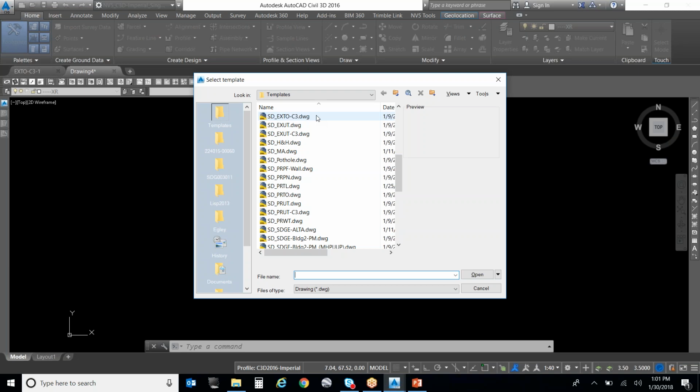So that'll be part of Mark's workflow here when he goes and builds a surface, starting with the aerials, and then what do we do when we get survey data, what type of survey data it is, and be in contact and communication with your surveyors. If you need better data, more accurate data in a certain intersection, or where you're doing a handicap ramp, or some critical data, hey, communicate that to your surveyor. Make sure they understand what you're doing so that they can give you the data that you need and to the level of accuracy that you need.